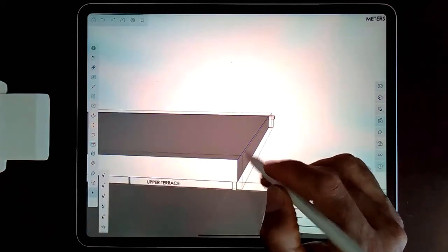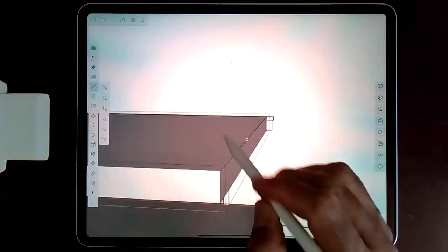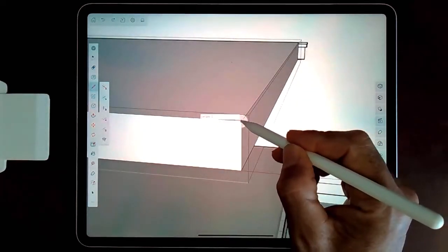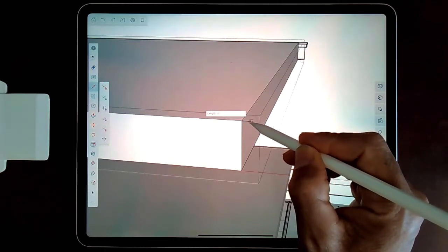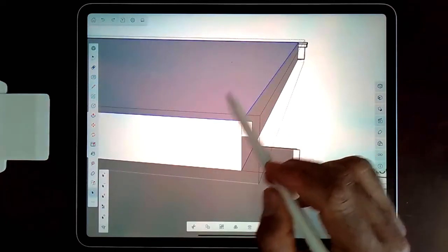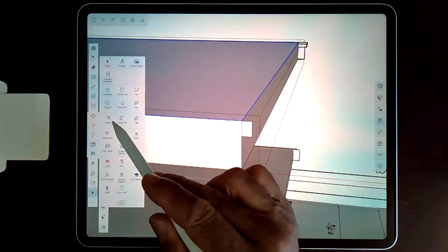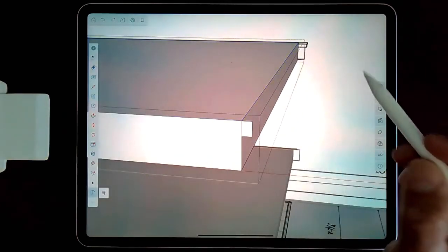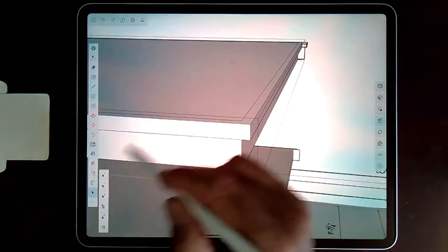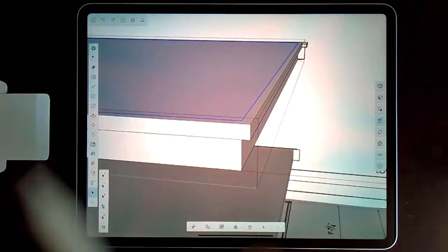So we're going to go into our roof assembly here and the roof slab and draw a small rectangle here that's representative of that fascia. We're going to bring it out 2-3 inches and then come down another 6 and then back onto itself. Now we can select the top face and go into our follow me tool and do a long click on that face, and there you have it. You have the fascia surrounding the entire roof structure there.